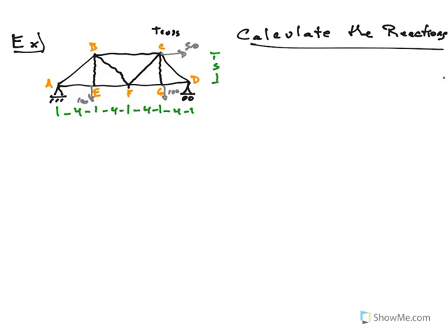So, as usual, my first step is let's look at the supports and see what are the available reactions. At A, there's a pin support, so there's going to be a vertical reaction, AY. And there's going to be a horizontal one. I'm going to call the horizontal one pointing to the left. And the reason is because I see that there's a horizontal force here that points to the right. So obviously, if I want to balance it, likely the reaction at A will be to the left. All right, so those are the 2 reactions at A. What about at D? D is a roller, so there's only a perpendicular one. So I'll say there's a vertical reaction called DY, and it'll point up. So there are my 3 unknowns, AX, AY, DY.